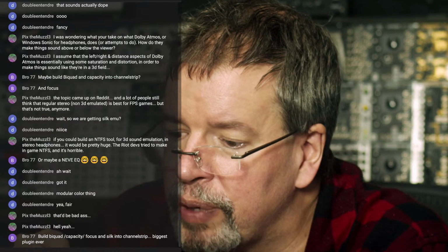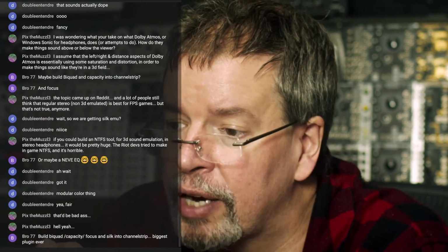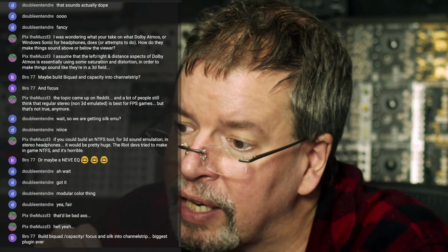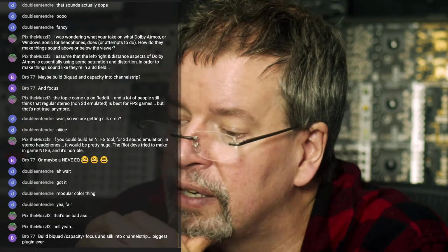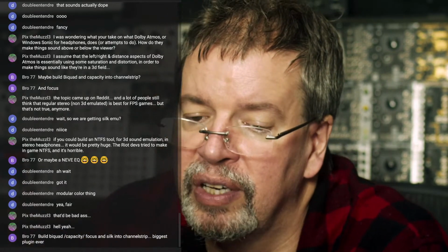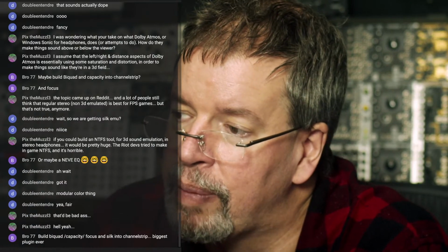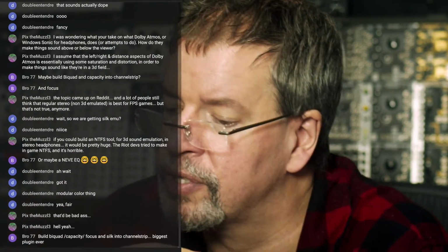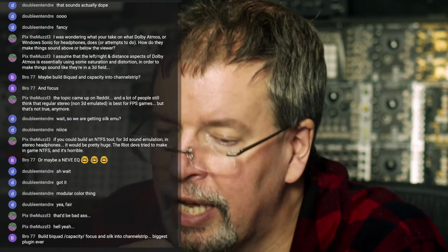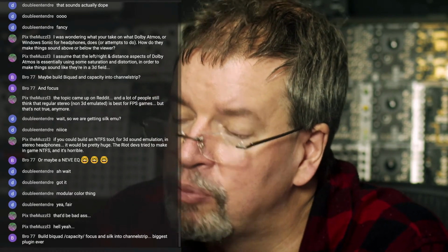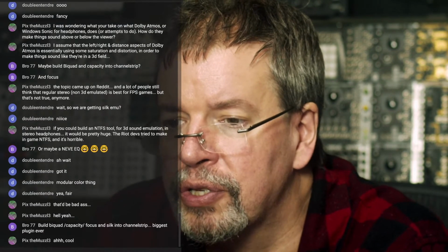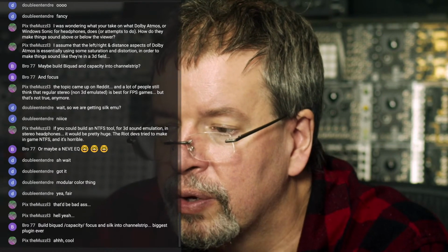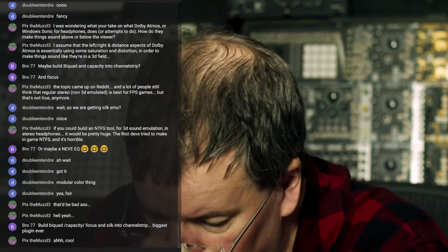Oh, bro, you're just throwing names around. Channel strip is always going to be a particular theme, but it is not unthinkable to have a channel strip that's based on my biquad filters because those let me get a little steeper. And the interesting thing about that is if you have a filter which has a cutoff and the cutoff, say, is maybe a little bit peaky, you'd have a high frequency cutoff and you'd be building it out of a somewhat resonant low pass. If you assemble things the way the channel strip does, you can assemble them in such a way where flat is still flat.